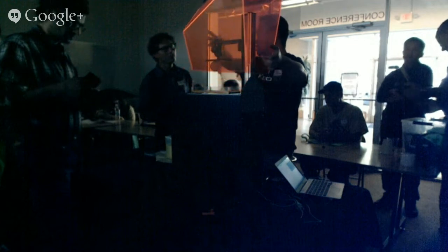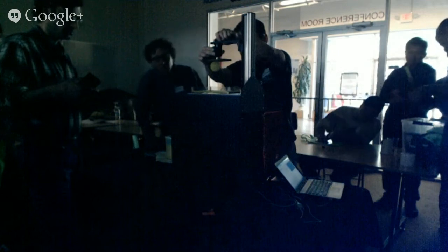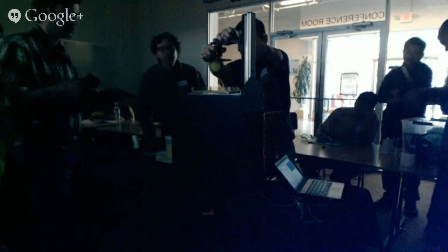I don't want to because there are components in the resin that will evaporate. The resin will still work, but then it's not quite the same. It's a little thicker, strange things can happen to it. But that's not the greatest storage medium. I'd much rather have it back in the bottle. But the 3DM resin, every minute it's in the vat, you're counting down time on the sidewall. And so that one, they say you really want to clean it up as soon as you're done, because every second the resin is in there, the life of the vat is counting down.